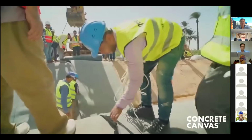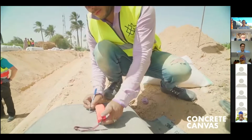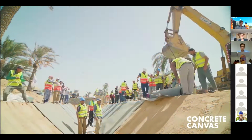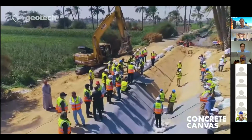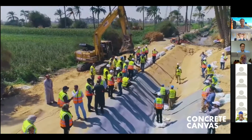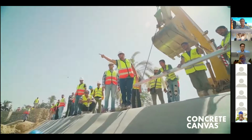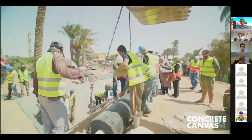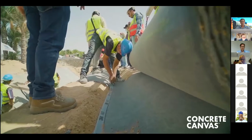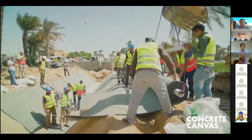CCX barrier was lifted into position and aligned transversely to flow in the canal by excavator. A double width spreader beam was used to deploy the 20-meter long by 1.9 meter wide rolls, which weighed approximately 600 kgs each. Material was drawn off the spreader beam by hand using a rope and labor positioned on the opposite bank of the canal. A concrete cutting disc was then used to cut these rolls to length.